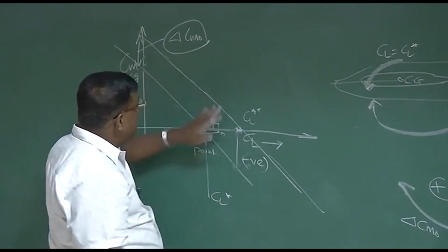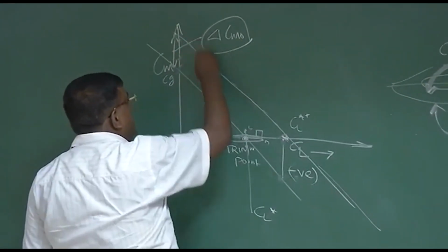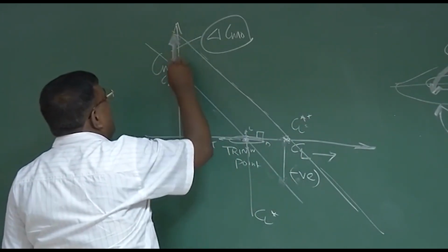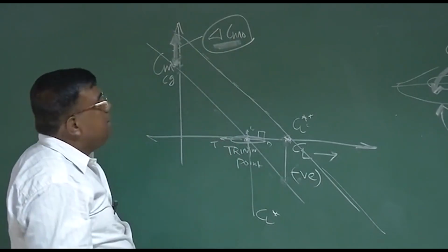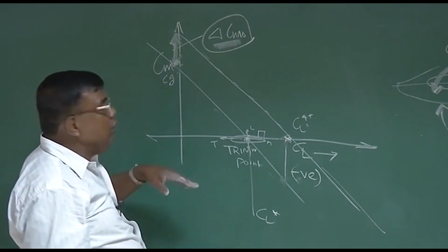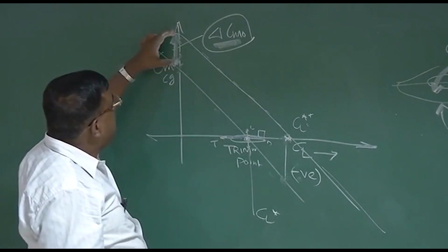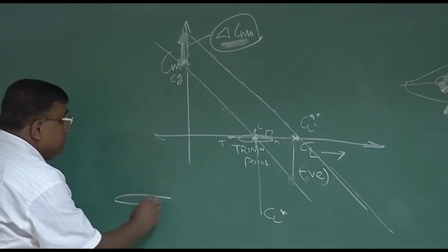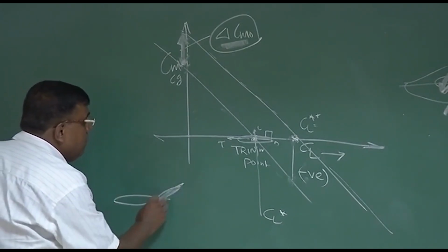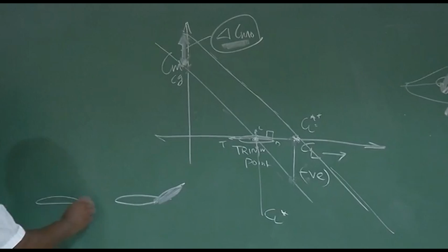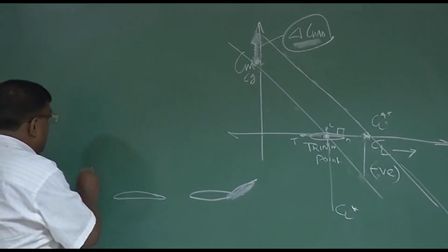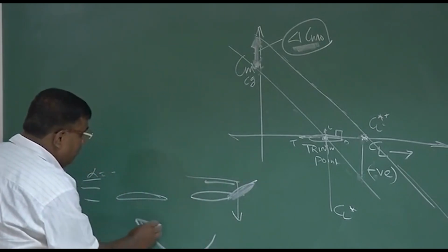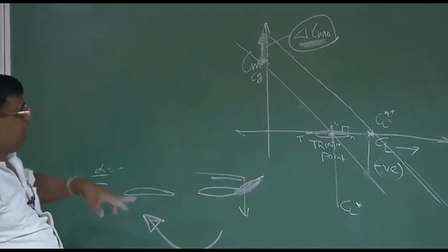If I try to explain through this graph, if I want to fly at this CL, which is CL double star, I have to add additional delta Cm naught. And since elevator deflection doesn't change the stability, slope remains same, to add this delta Cm naught, I have to put the elevator up, and definition of Cm naught is Cm at alpha equal to 0, this is the wing, at alpha equal to 0, there is a force downward which gives a positive moment, that is in our case delta Cm naught.